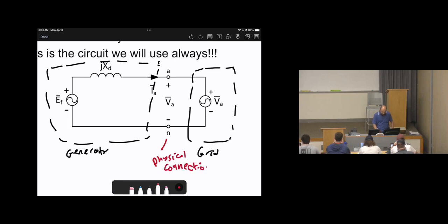And this equivalent circuit is not 100% true. Again, why? Because I neglected Ra, I neglected Z grid. I assumed them very small, so they are negligible. So this leads to an accuracy in the 90s, not 100%, but in the 90s. We can say 95 is acceptable. Then that's fine. If you need higher accuracy, if the accuracy really matters for the application, then you need to use the original model.